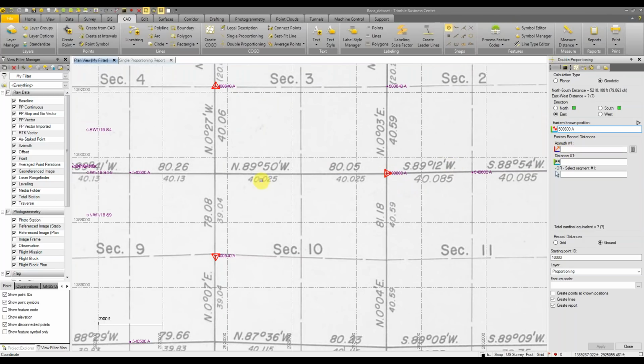To the east, this is north 89.50 west, and the distance, and there's the two quarter section lines, or there's the full section line here, 80.05 chains. For those not familiar with chains, there's...